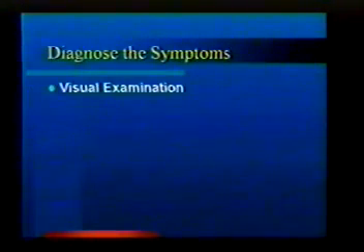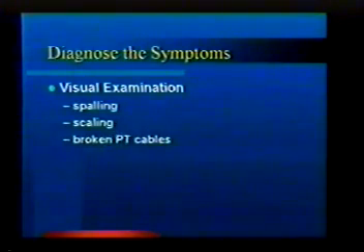Diagnose the symptoms. Of course you've got your visual. You've got to be looking at what you're seeing. We could be looking at spalling, or we're looking at scaling. Which one are we actually looking at? That's with your eyes. Do we have broken PT cables? Do we have crack patterns? Each different crack pattern may have a different source in the problem. You saw that earlier slide of the flexural cracks. I'll talk some more about other types of cracks.